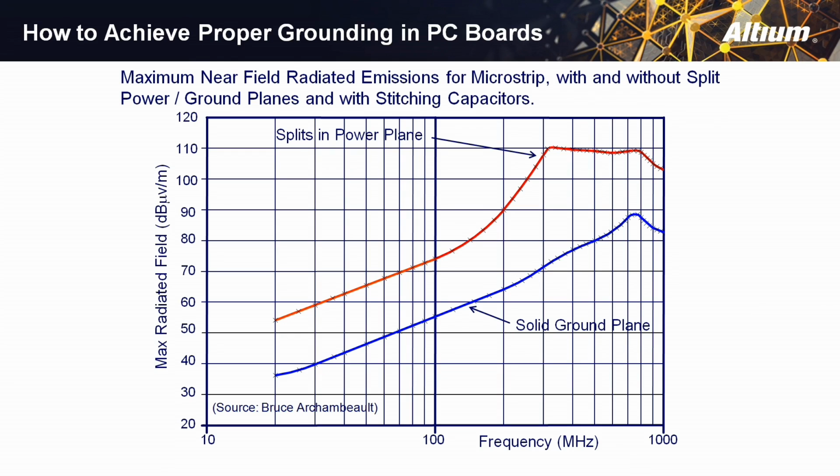And the message here is, can you route across the split power plane? The answer is yes, but only if they're close together. Power is close to ground. And yes, if the signal is not terribly high frequency. In this particular case, you can see routing across the split between layers 3 and 4 of a 4-layer board was an absolute living disaster.